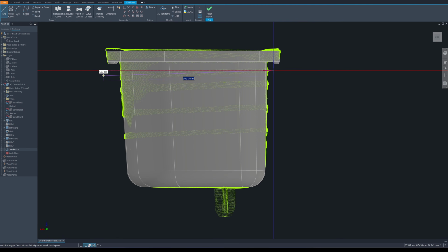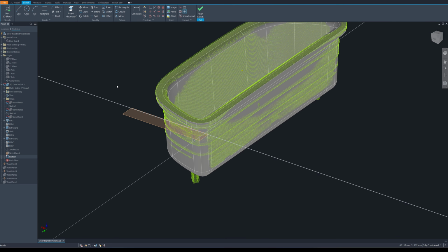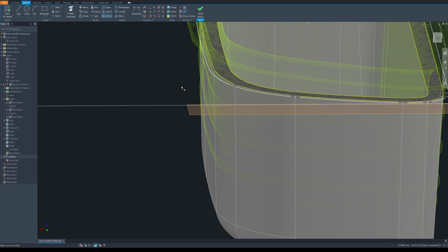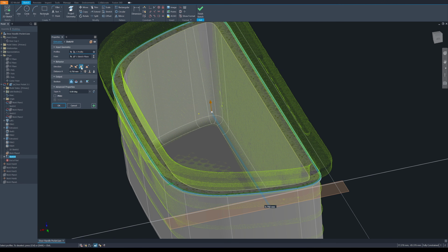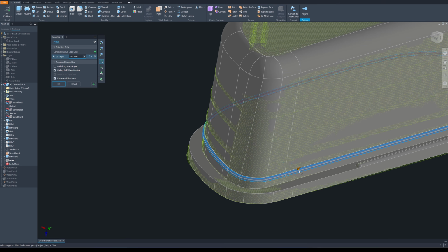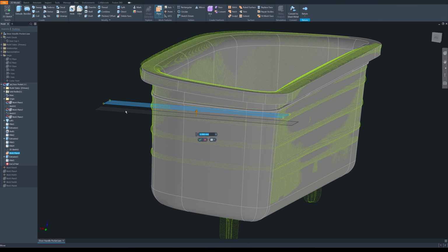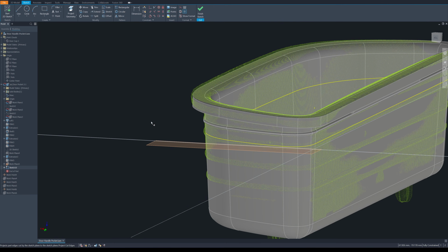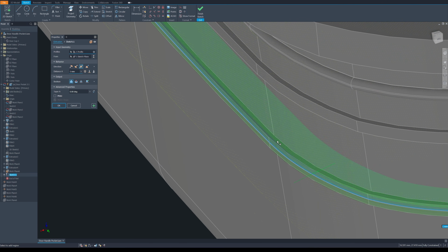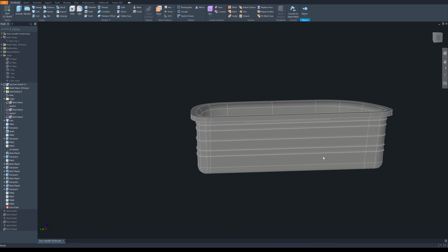Now, I'm using 3D lines to define a plane, which I will use to create a strip around the body of the pocket. Since the pocket's profiles vary along its length, I will project the cutting edges from the sketch plane and offset them outward instead of redrawing each one individually. After offsetting, I will extrude the geometry and then round the corners using the fillet command.